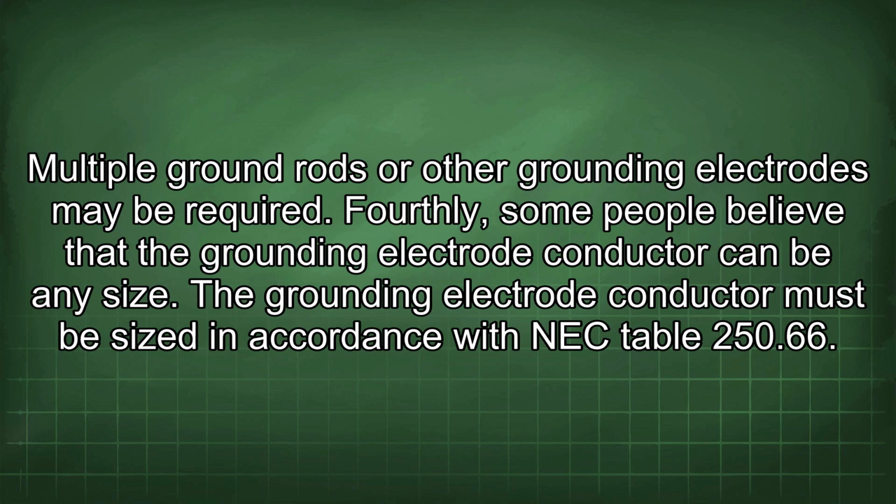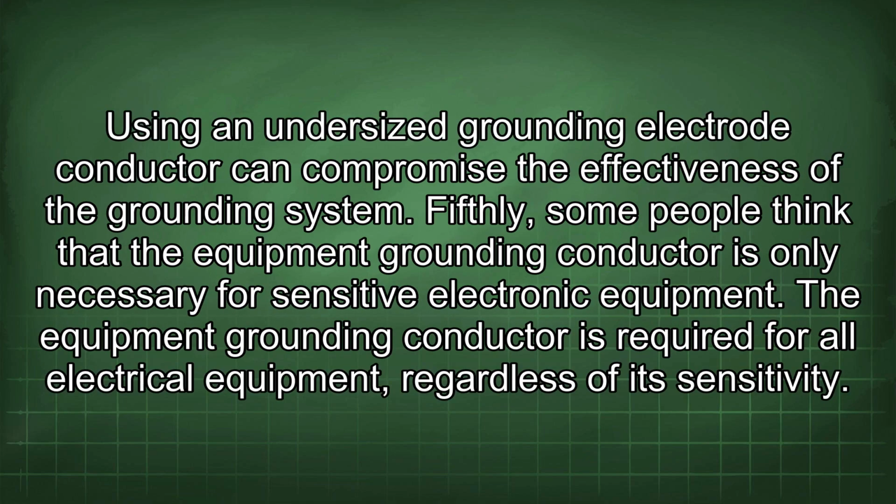Fourthly, some people believe that the grounding electrode conductor can be any size. The grounding electrode conductor must be sized in accordance with NEC Table 250.66. Using an undersized grounding electrode conductor can compromise the effectiveness of the grounding system.